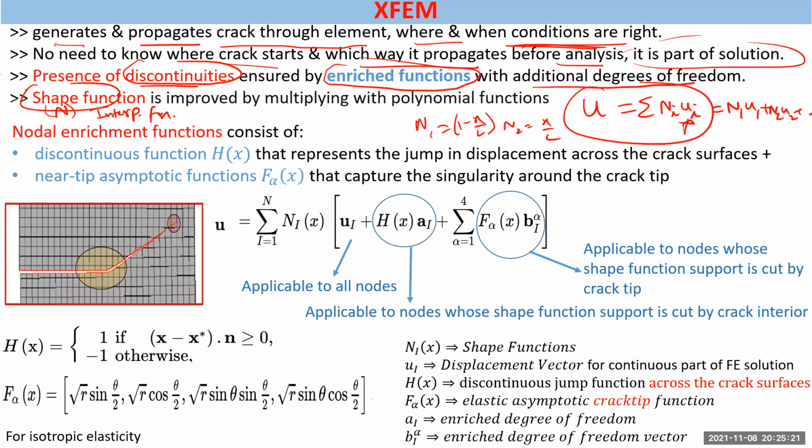And if you have displacement discontinuity, you have convergence problems. The only way to overcome it is to manipulate that shape function. So that's your displacement here. U is summation of Ni times Ui. Now the displacement is some big function here. That's the shape functions. The shape function is getting multiplied by Ui, which is the same as previous case. Plus you have two more functions coming in.